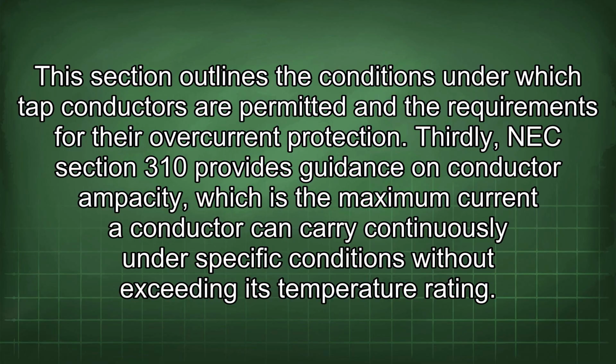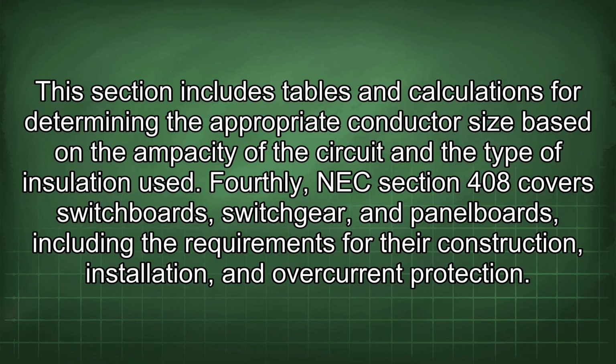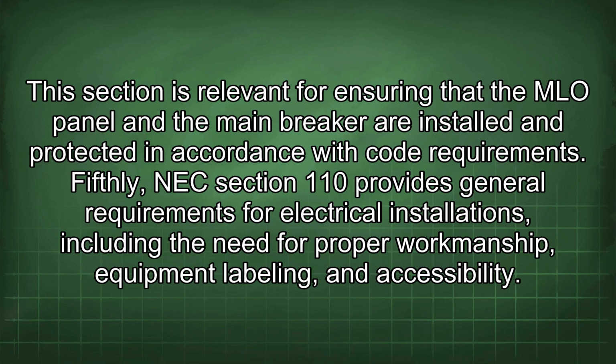Thirdly, NEC section 310 provides guidance on conductor ampacity, which is the maximum current a conductor can carry continuously under specific conditions without exceeding its temperature rating. This section includes tables and calculations for determining the appropriate conductor size based on the ampacity of the circuit and the type of insulation used. Fourthly, NEC section 408 covers switchboards, switchgear, and panel boards, including the requirements for their construction, installation, and overcurrent protection. This section is relevant for ensuring that the MLO panel and the main breaker are installed and protected in accordance